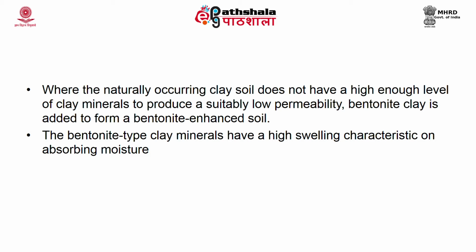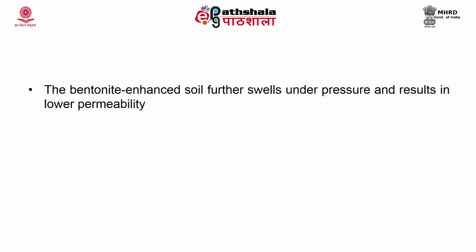Same as clay, as I told you, when there is moisture the particles will absorb moisture and start swelling. The same characteristic is also available for bentonite type of clay material, where it absorbs moisture and shows a high swelling characteristic. Further, it is not only moisture that plays an important role in leading to low permeability of bentonite clay.